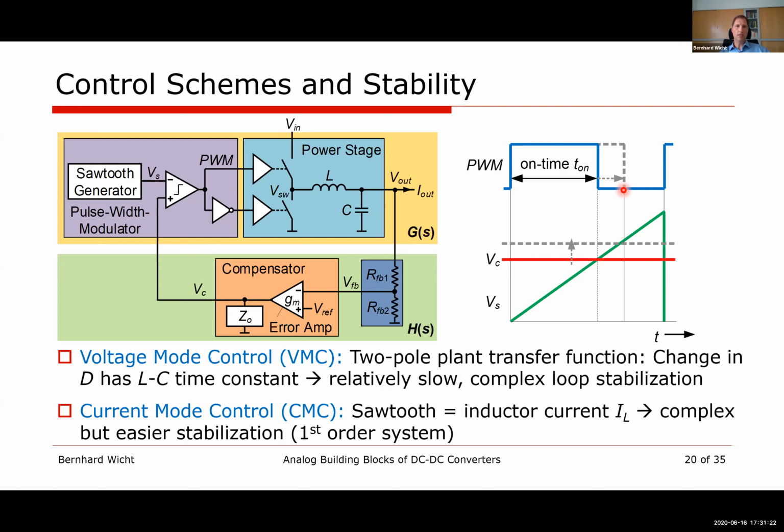So we basically see both noise contributions: a broadband noise coming from this rectangle, trapezoid shape, and the other one is a smaller band, which is current ringing. That usually occurs as a peak in your spectrum in the 50 to 100 megahertz, few hundred megahertz range.